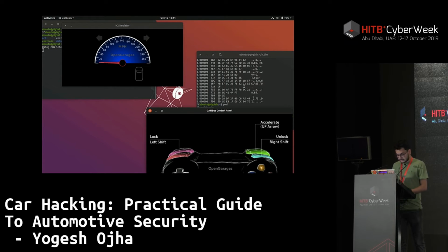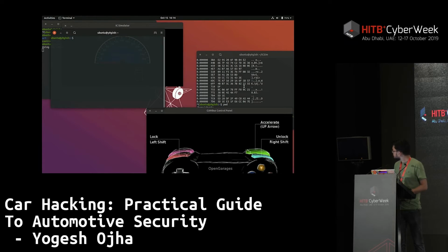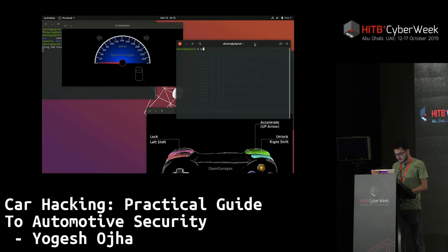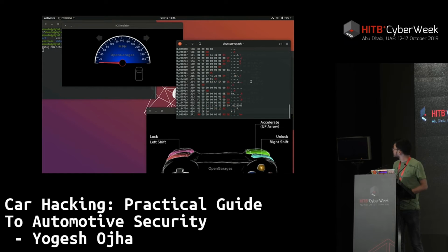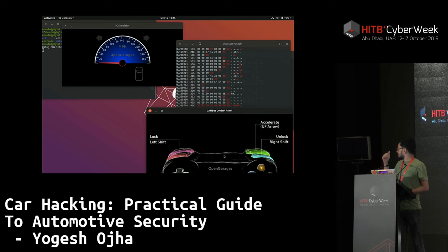Now let's perform the replay attack. And if you want to see how exactly the data is being sent, I can always run cansniffer -c vcan0. So you can see all the changes in the data here. If I press left and right, you might see one of these data being changed in one of these IDs. I reverse engineered the packets and found this arbitration ID by dividing it into one half, the other half, and the same way, you can spend your time finding out what exactly is the ID that the packet is being sent to.